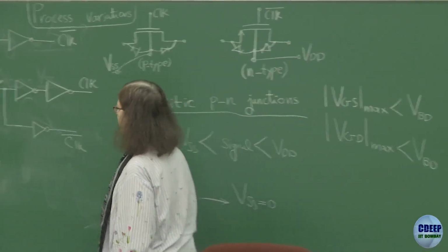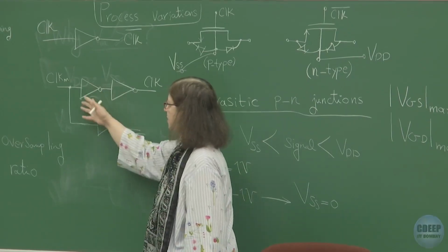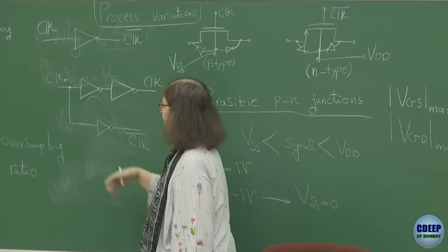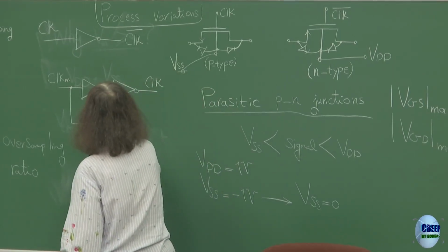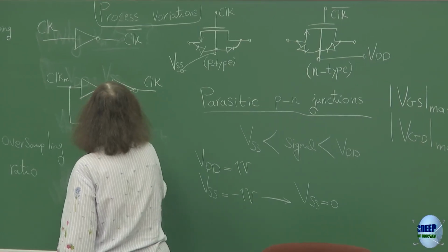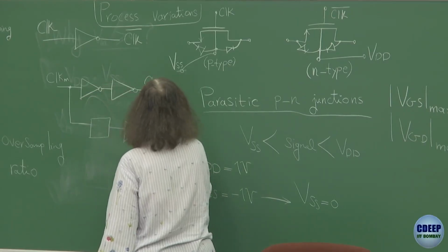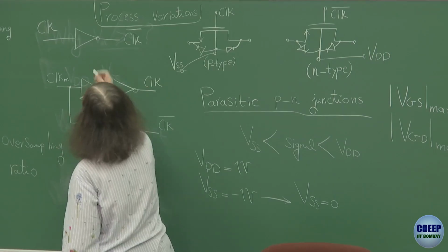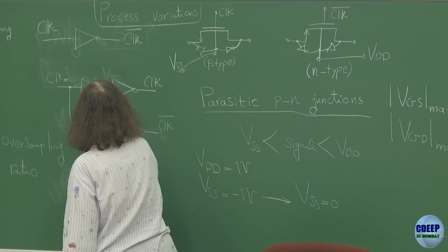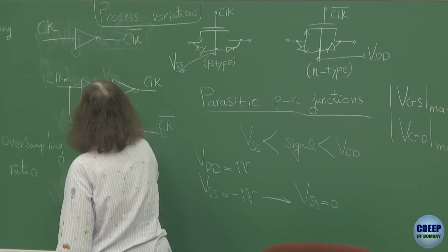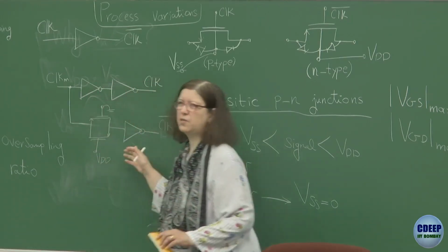There are other techniques, for example what Razavi says: instead of this, say for example a path, let's put two inverters and then have complementary switches and then put an inverter, and still try to make them matched. See, exactly the same transmission gate. Eventually it's a transmission gate, but in analog it is like an analog switch, and they are always on. Like this is grounded, this is VDD, and then he says, but this also doesn't work.